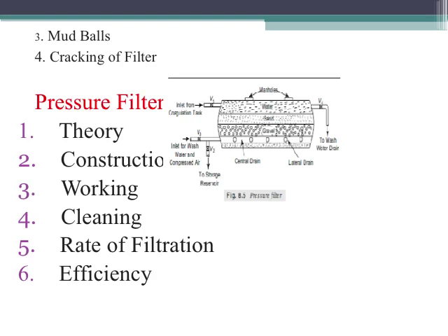They can remove turbidity only up to 35 to 40 NTU, but since the water entering these filters is given pre-treatment in the coagulation sedimentation tank, it is comparatively less turbid. Such turbidity can be easily removed by these filters and brought to the permissible limits. And as far as color removal is concerned, they are highly efficient and can bring down the color to as low as 10 on the cobalt scale.